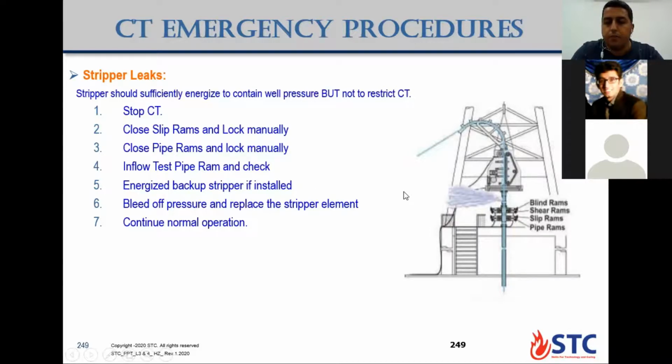Yes, Mr. Khawar. My question is, do we always have to close the slip rams first, then the pipe rams, or can we close the pipe ram first and then the slip ram? No, you need to close the slip first, then the pipe. The slip will hold the weight and the pipe ram will seal. If you close only the pipe ram, maybe the coil tubing will slip through the pipe ram, because the slip holds the body from outside. That is needed to hold the weight of the coil tubing. The slip ram is also not a sealing ram, as we said yesterday, just to hold the string weight.